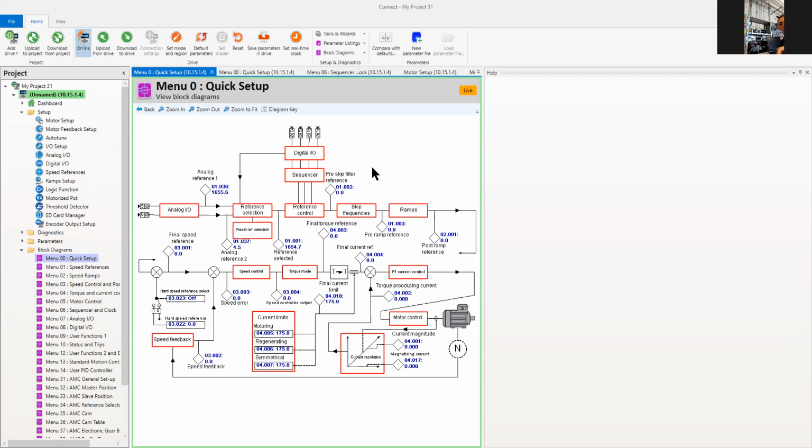Hey, David, I just had a question. I noticed you using, I think, 1,725 RPMs, if I'm not mistaken. I also noticed it was at 4 poles and 60 hertz. I remember previously you stated that at 4 poles we use 1,800 RPMs, and here we're using 4 poles, 60 hertz, 1,725 RPMs. What's the reason for reducing the RPMs? It's the slip factor, right?